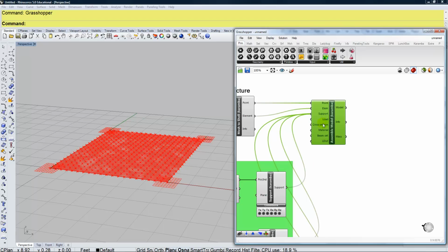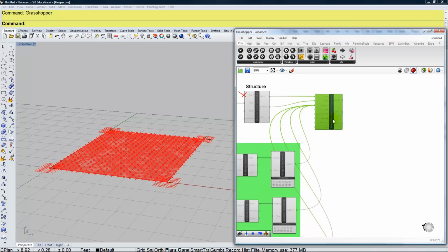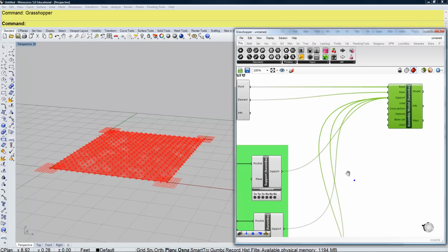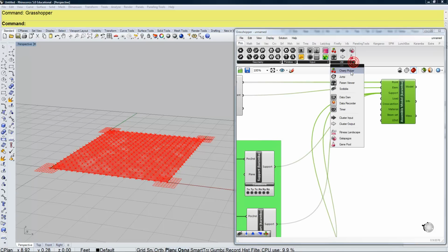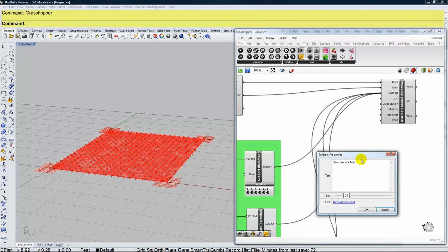The next thing that we need is a load to raise this mesh up and make it form found. So I'm gonna go ahead and move this assemble over and start to create the load. And I'm going to use 2 point loads. So I'm going to go ahead and make a scribble, and I'm going to name these point loads.